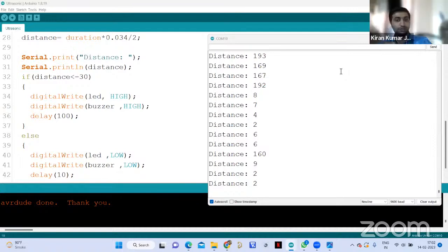As I've told you, you have two options over here. This black jack, you can connect from this also. It will give you 5 volt, it will give you 6 to 20 volt. From this jack you can give the power supply to the board itself from 6 to 20 volt.